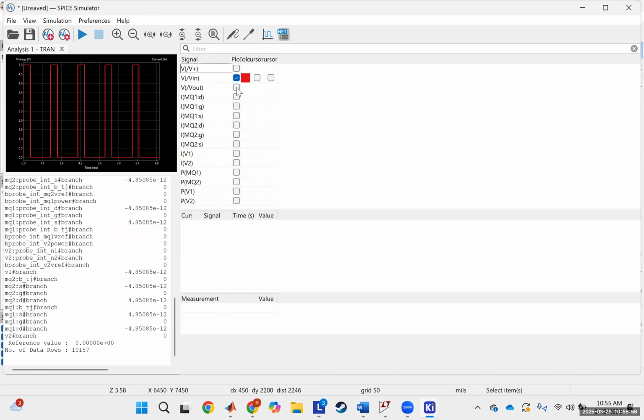That's because if you look at our input voltage, it's only going high for half of a millisecond. It's going high for a fourth of the period, even though our period is still at 2 milliseconds. So that means it's high for half a millisecond and low for 1.5. And then if you go look at your output, you'll see this reflected. You'll have it low for that same period of time and then high for that same period of time, even though our period is the same.